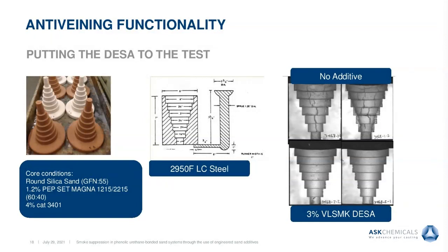So yeah, we've now done comparison smoke suppression testing with this additive in phenolic urethane no-bake and cold box, and we already know that we had to make adjustments to the blend to be able to suppress the smoke at the same level as we're doing for the PEP set for the cold box. I think there's a little bit higher smoke on the cold box, so we need to reformulate the blend a little bit to get there. So we're working on that.